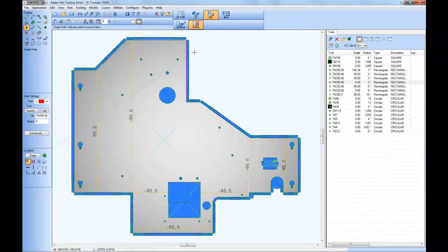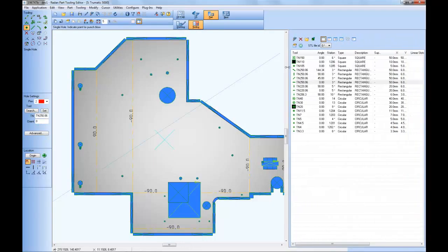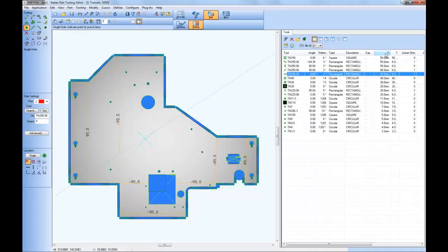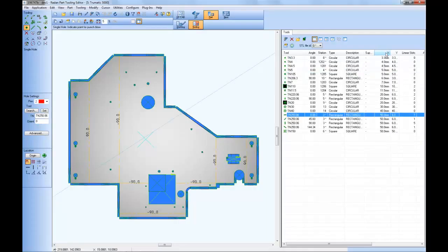When the dynamic tooling list is displayed in Details view, the current display type, you get the detailed information, and the column headers now allow you to sort the list by any of those column types, such as by tool size, sorting the list from the longest to the shortest tool, or vice versa, or by tool type.